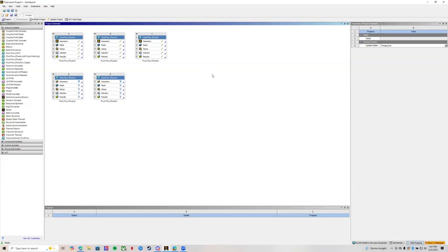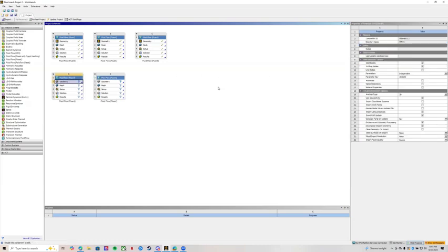So first thing we're going to do is open up ANSYS. We're going to make sure we have two Fluent flow systems. We're going to go ahead and select them, and make sure that they're in 2D. That's what we want. So we're just going to do that real quick. First things first, we're going to go to our geometry. We'll make sure we open up Design Modeler. We don't want to open Discovery.